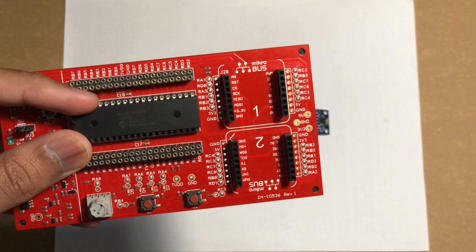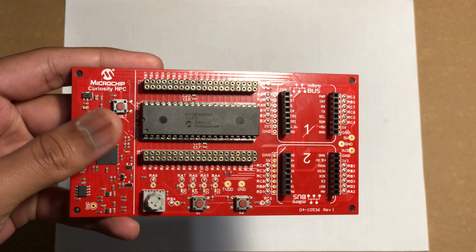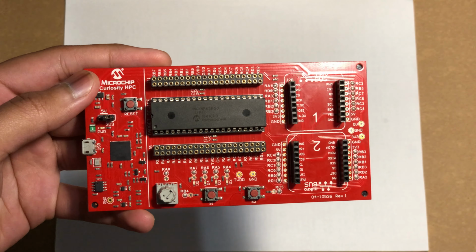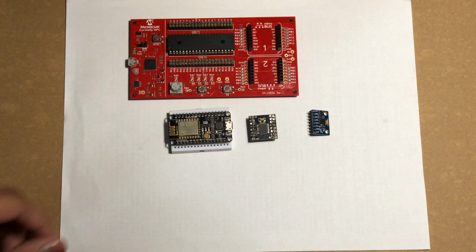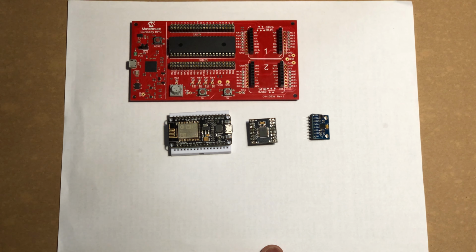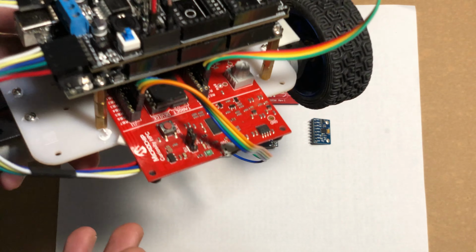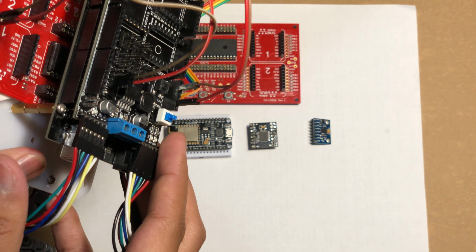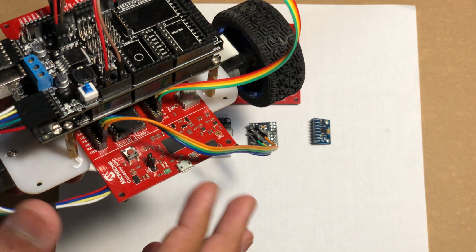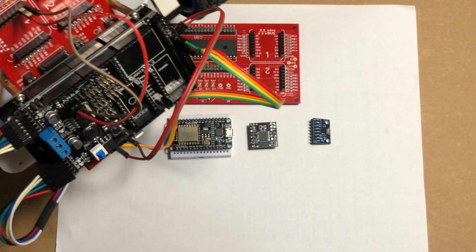the PIC18F45K50, which is an advanced 8-bit microcontroller that has a high performance core, flash program memory with self read and write capability. It has an internal clock of 48 megahertz, which helps us get real time feedback. It has 36 input output ports and supports I2C, SPI, UART, and USB 2.0 protocols. Last, we have taken a small help from Arduino Mega 2560 to perform complex math calculations using Kalman filter and 3D angle calculations to perform the balancing of the robot by supplying the required pulse width modulation output.